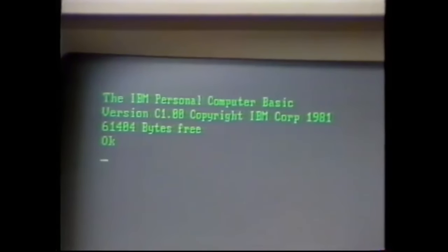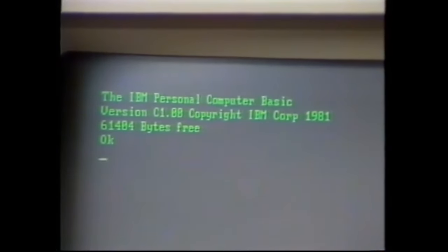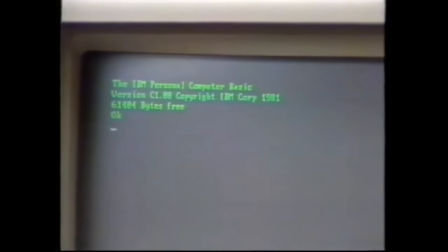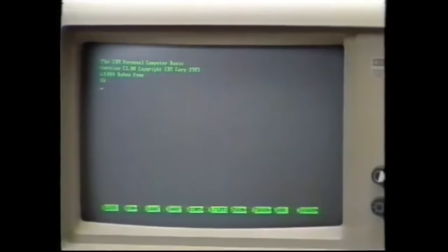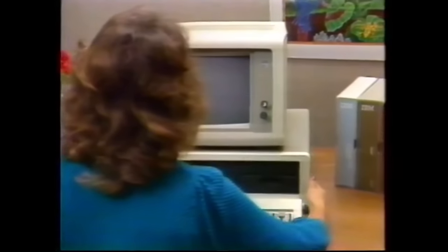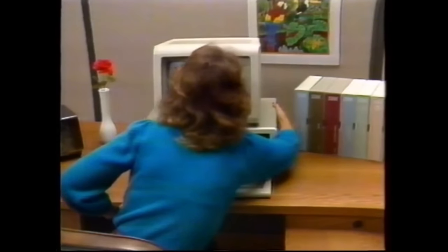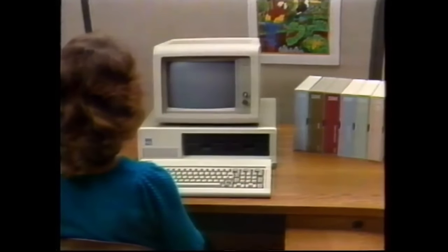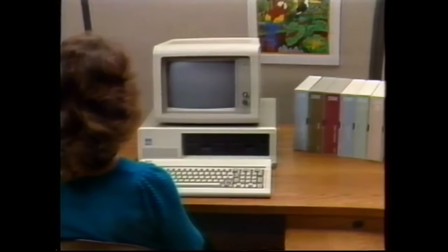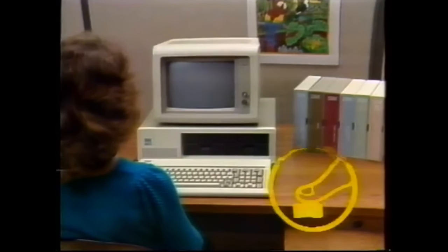If you didn't get any or all of these three responses, the cursor on the screen, the short beep, or the display, you may have a problem with your system. If this is the case, turn the power to your computer off and wait 30 seconds before you turn the power back on. Some IBM PCs will reset in a shorter time. You'll have to experiment to find the shortest recycle time for your computer. For now, wait about 30 seconds. Then turn the power switch back on. Watch and listen for those three responses.